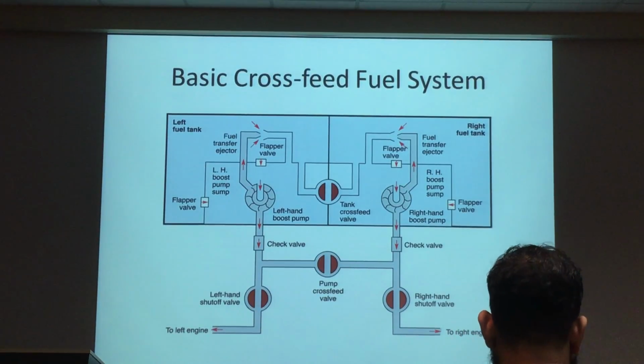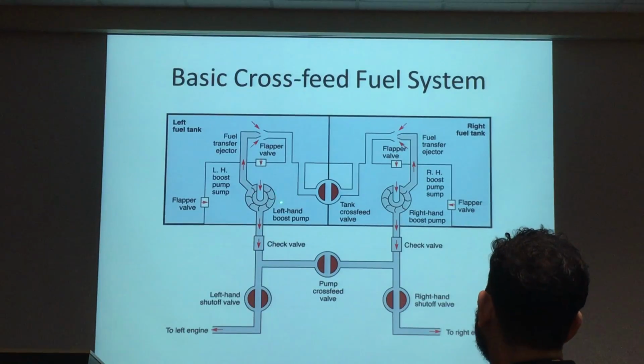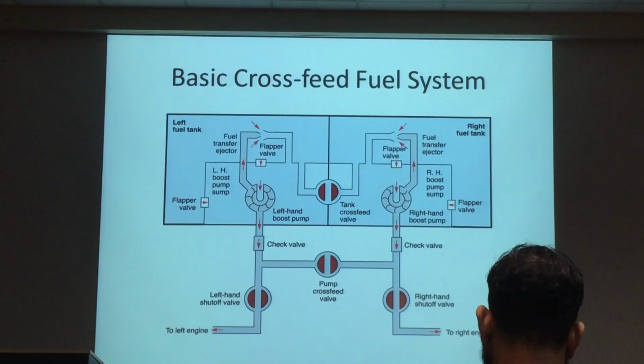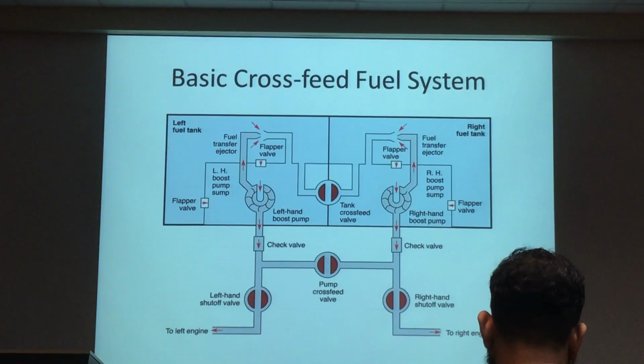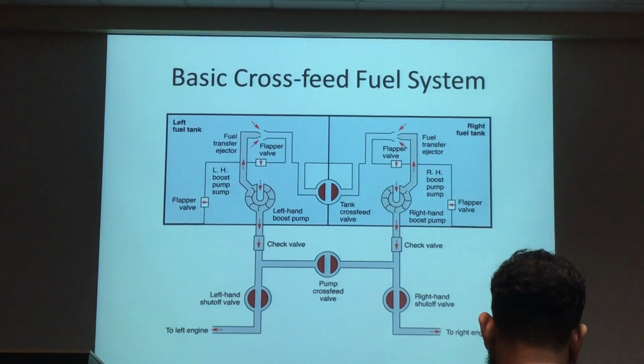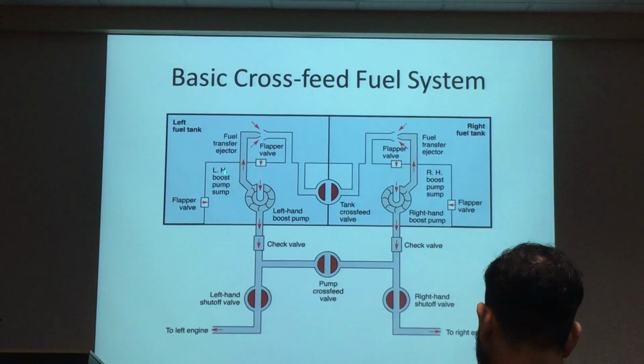Remember you've got two kinds of pump. This is your fuel boost pump, a centrifugal fuel boost pump. This is the injector pump. Okay, the other pump is your engine or steam displacement pump. Three kinds of pump. The injector pump, without the motive force, won't work. It's a kind of slave pump. When this pump is working, it will suck. When this pump is not working, it won't suck. Okay? Understand?